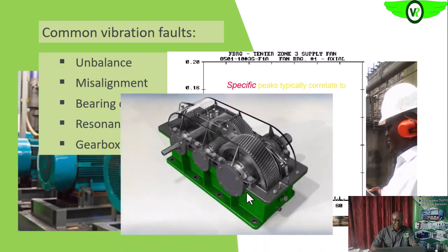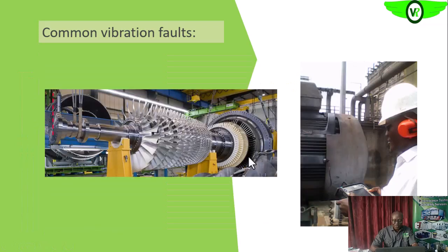So this is the gearbox that we're talking about. The speed of rotation times the number of teeth that you have on this gear will give the gear mesh frequency. Like we said, we'll look at them in a little bit more detail.